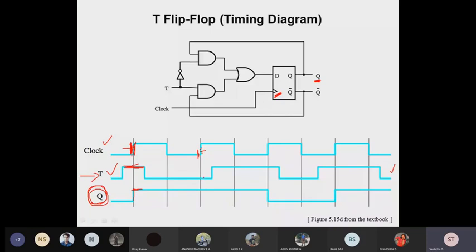But at this location, your input value is in the position of 0. But you know very well, each combinational circuit has some propagation delay. This and all you might have studied in your carry adder and all, right? So there will be some propagation delay. In order to transfer the information from this location, this AND gate has some delay, and this OR gate has some delay, this has some delay.